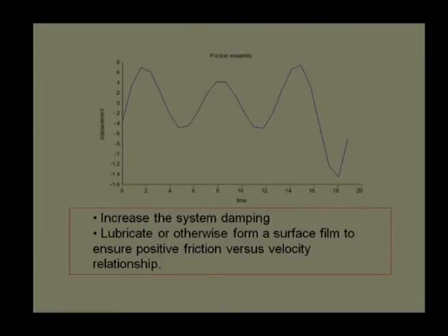This is the reason why I have given the example of hydrodynamic bearing. In hydrodynamic bearing, I mentioned that at start the coefficient of friction may be very low, 0.1 to 0.15, and when we are operating it at the fully developed condition, the coefficient of friction may be 0.001. There is a huge difference. If we operate that machine at a very low speed, naturally we are going to face problems. There will be more wear, there will be more knocking of the shaft over the bearing surface.